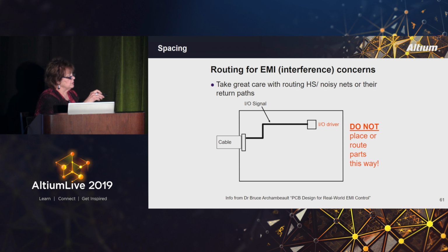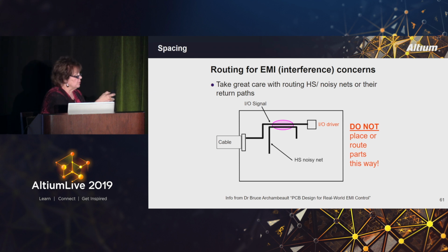So he's saying here, if you have a cable here and you have an I/O signal here, you want to have this particular part, which is probably the driver, as close to here as possible, because if you have it over here, there's a good chance that you could pick up noise from other signals. This noisy signal here might happen to route close to this particular signal and could easily put noise onto that I/O signal, and now that I/O signal can carry it off the board into a cable, and that cable could then radiate and be an antenna and cause all kinds of issues.